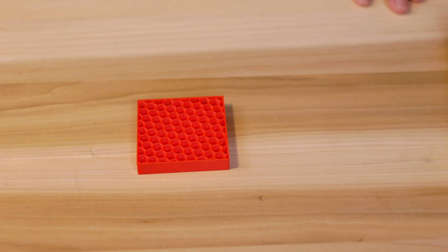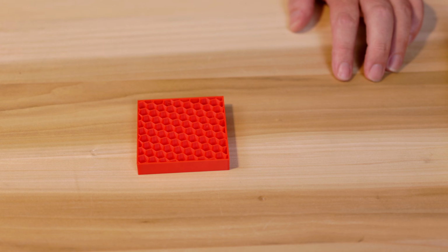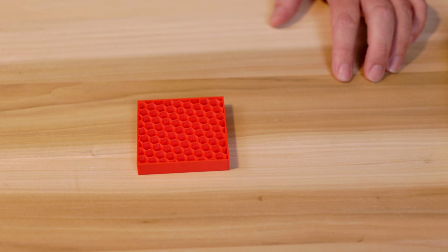All right, next on the list is honeycomb. And a honeycomb is a hexagonal pattern resembling a bee's honeycomb, as we can see here, right? The use case is structural components requiring weight efficiency. So the pro is excellent strength to weight ratio, and the con is it is longer to print, and one of the longer ones to print. Printing tip, ensure proper extrusion multiplier for this intricate pattern.